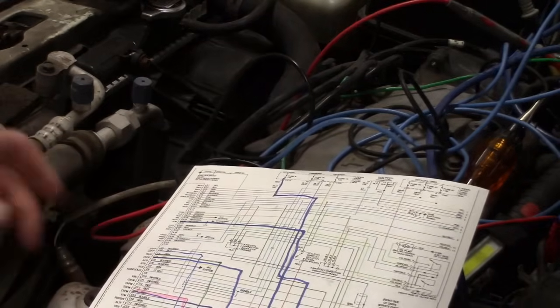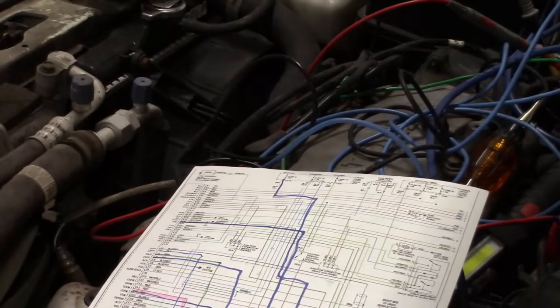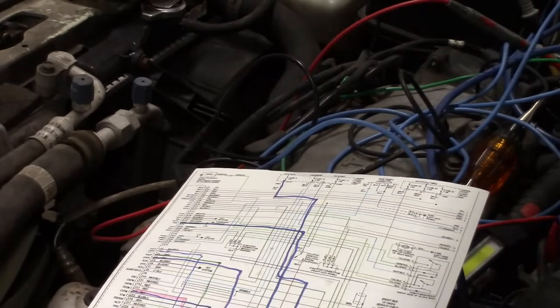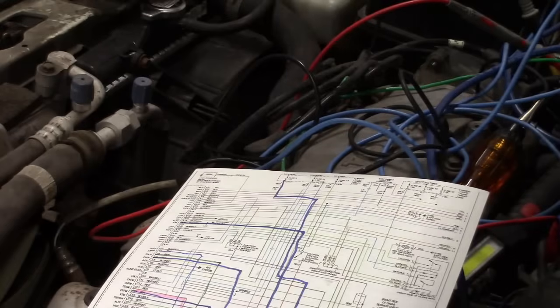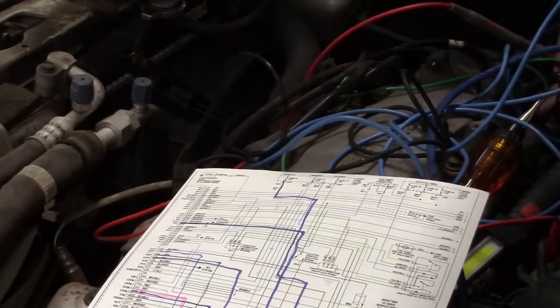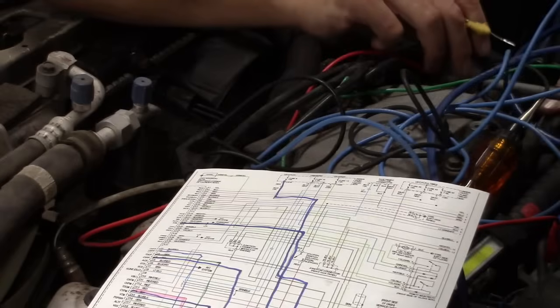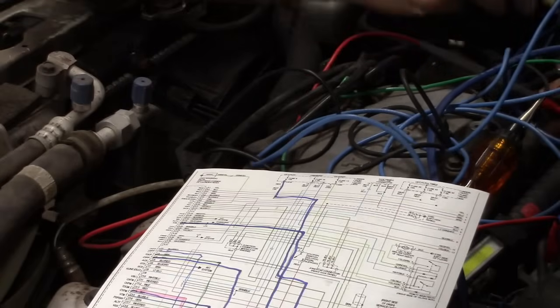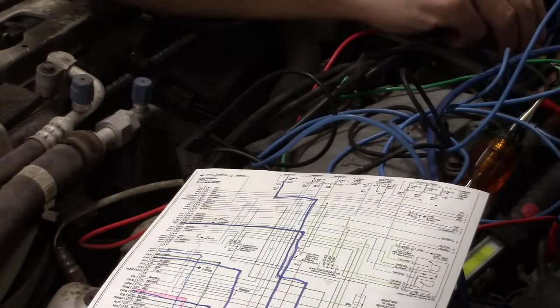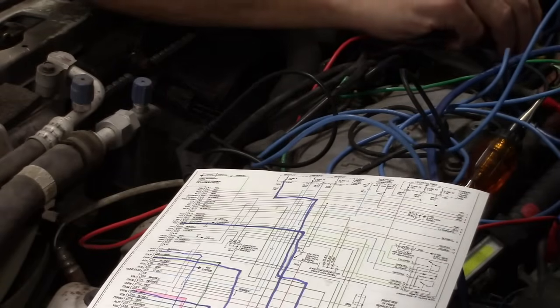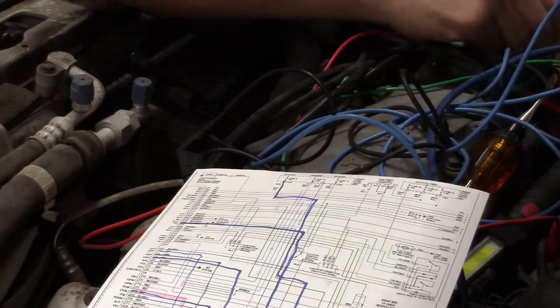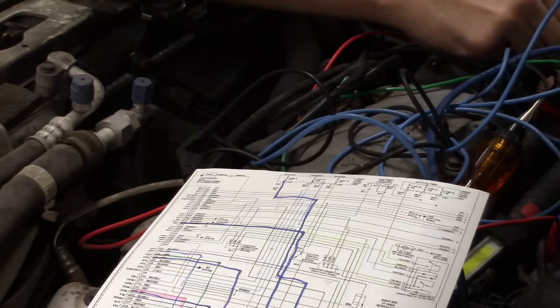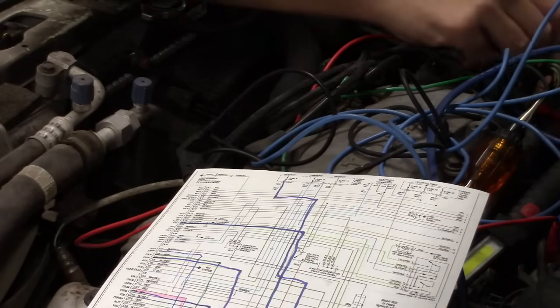All right, again, looking at our sheet here, crankshaft position sensor, we know we've got white coming in, yellow with blue coming out, but that was not correct. So I'm going to go to this white coming in, and it's a white coming out, and that's all right. It's not what our diagram says, but our diagram is incorrect on that. I am sure of it.